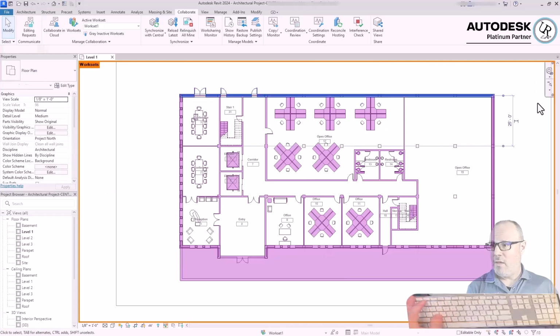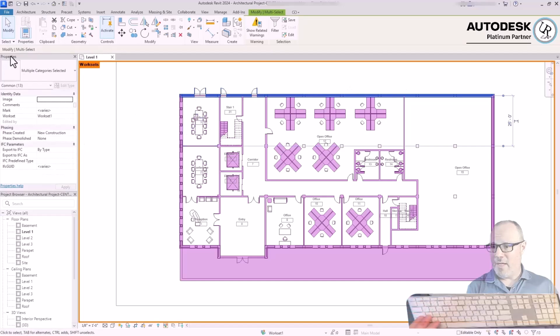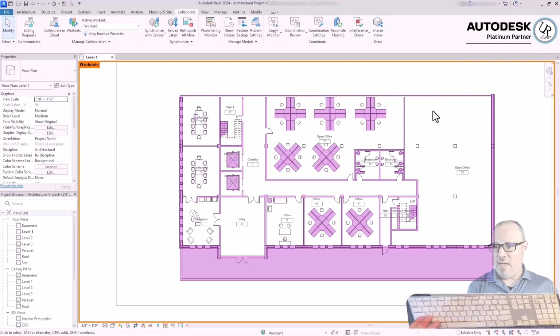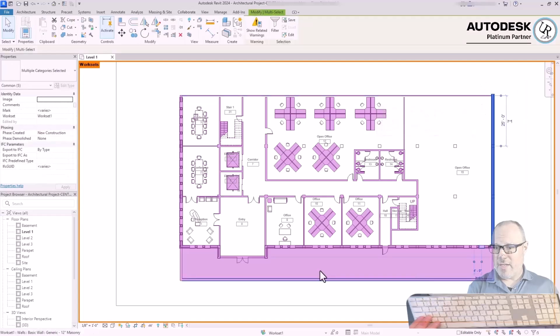To do this, you'll select a group of content, go to the Properties window where it says Work Sets Property, choose the work set 1 drop-down list and change it to a specific work set like exterior. It now makes that invisible because I've hidden that in the view, and you'll go through a process of continuing that around the rest of the building.